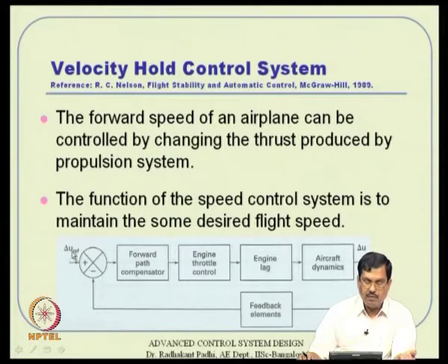Delta U is the difference of speed, basically the reference speed. So, anyway, you have this actual information which you can sense using, let us say, an air data system or GPS system and things like that. Depending on whatever your required value is, you generate an error command, and then you multiply that with some gain, or if necessary you derive this rate so that you can talk about PD control, or do this integral manipulation here.